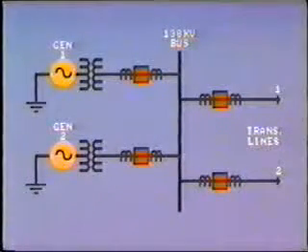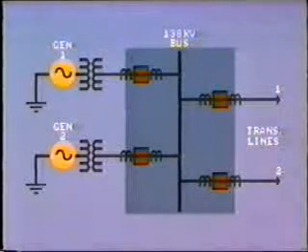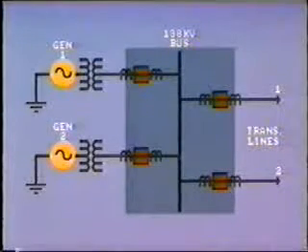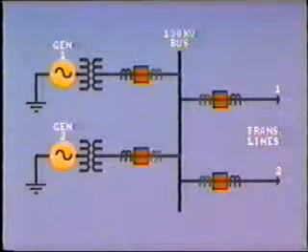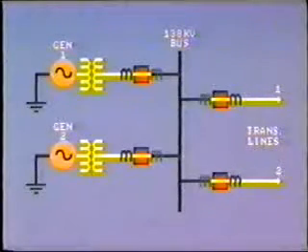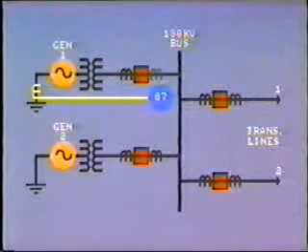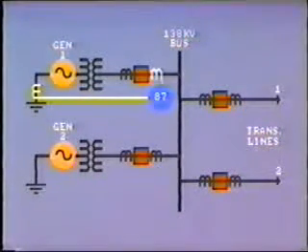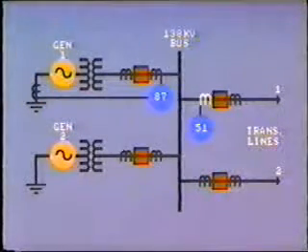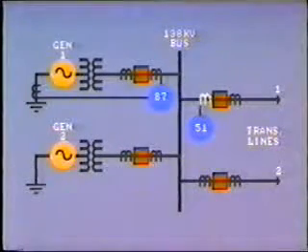The most simple is this single bus arrangement. The protected zone can be shown by this area, which extends to the outboard bus protection CTs. The inboard CT in each case is used for protection of the connected circuit. For example, in the case of an incoming generator, this CT may be connected to the generator differential. For a transmission line, this CT may be part of overcurrent or distance relay protection.